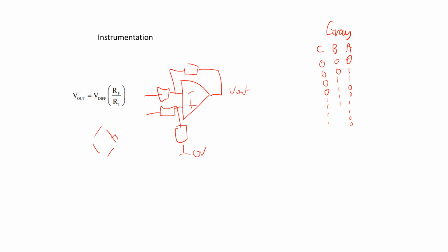Okay, and sometimes they ask you about revs per minute and things like that with slotted discs. So sometimes they might give you like a slotted disc type thing like that. And say it's got 100 slots, it turns around 10 revs per minute, how many slots are counted. So you just need to logically work out what's going on. So turn it into seconds and things like that, revs per second, or it might say how many counted in a second or whatever. Yeah. So hopefully that's straightforward. So you're just using a bit of physics there in that one actually.